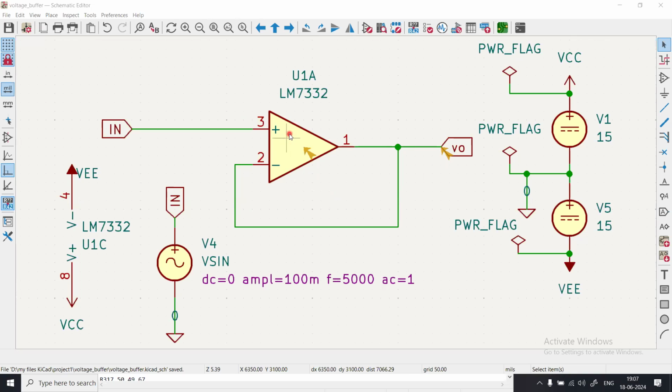So what you see here is an operational amplifier, which essentially has positive and negative input terminals. That's why it is a differential amplifier. It has one output. The basic fundamental principle is that we utilize negative feedback, where we feed all of the output back to the negative pin. That's why we call it negative feedback. So the feedback factor here is 1.